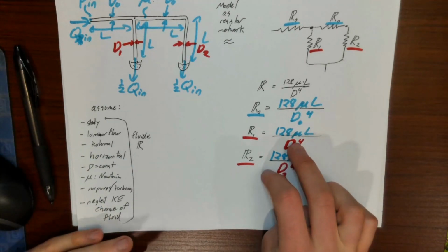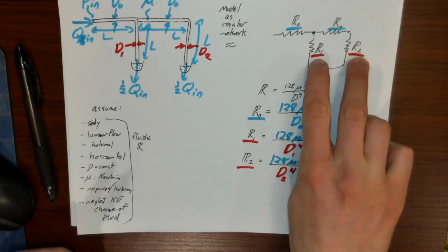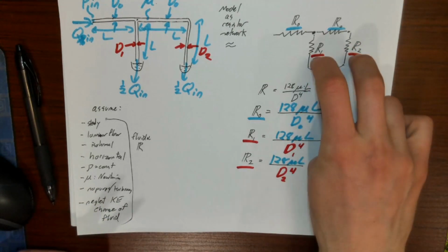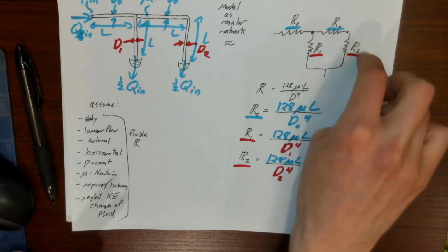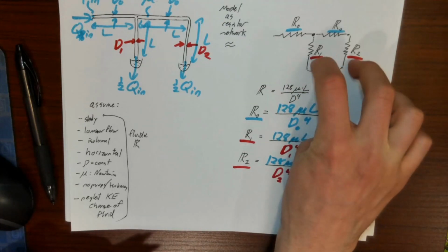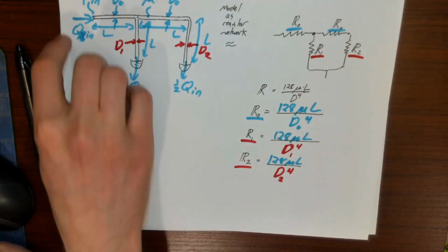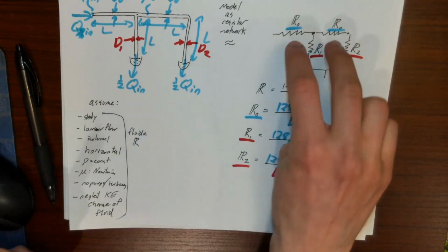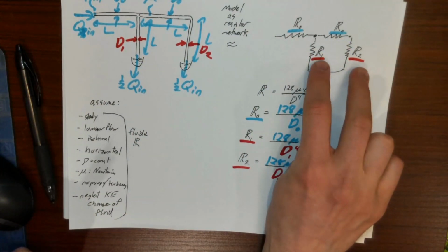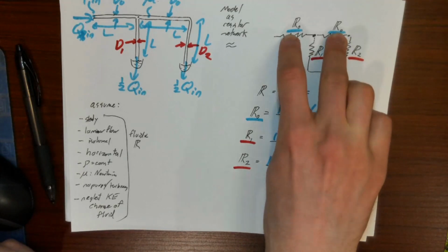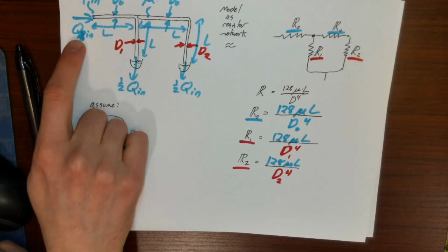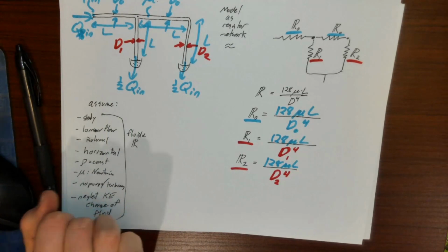So what's the deal? We have sort of two unknowns in our system. So we're going to need at least two equations to help resolve these unknowns. So we'll try to put the two unknowns in terms of the rest of the knowns of our system. For example, we'll try to put R1 and R2 in terms of R naughts, as well as in terms of Pn and Qn, and some of that stuff that's going on here.